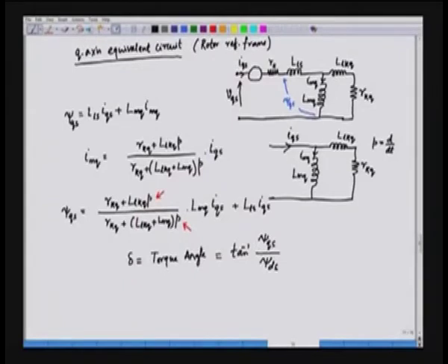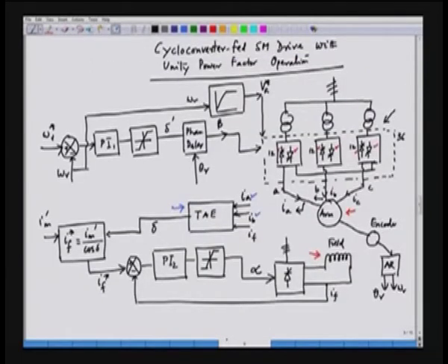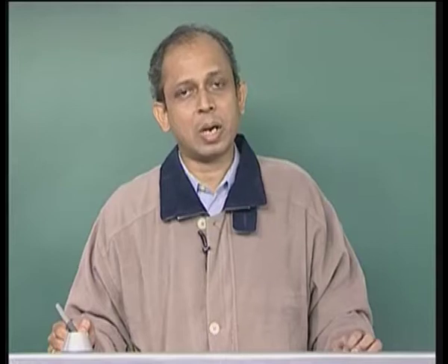control of synchronous motor. Now, we have also seen that in the synchronous motor control, we also need theta r. Theta r is the rotor position. Rotor is moving away. The d axis is moving away. The rotor is a continuously rotating member. And then we also need the expression for the speed. And these theta r and the speed are obtained using an angle resolver. Angle resolver stands for AR. So, the angle resolver gives us information about theta r and omega r.